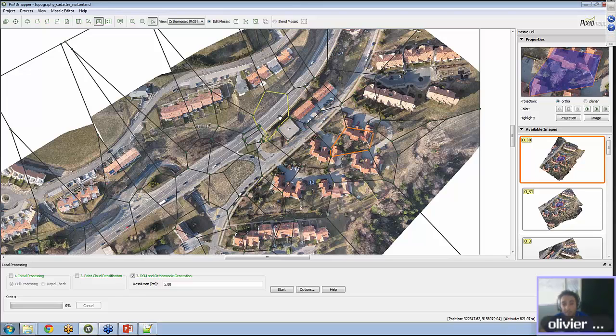It's a .p4s file that is stored in the same folder where the project is, under a folder called view_mosaic_editor, which is at the same level as 1_initial, 2, and 3, the outputs from the other steps. The fact that we have it there does not mean that the output is created. We need to create the output.